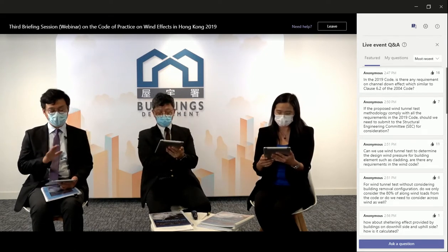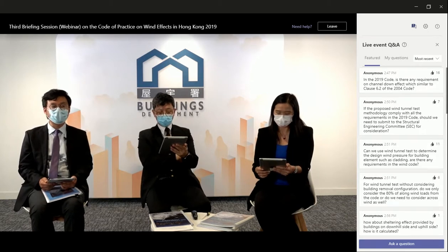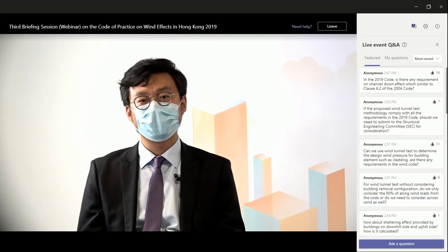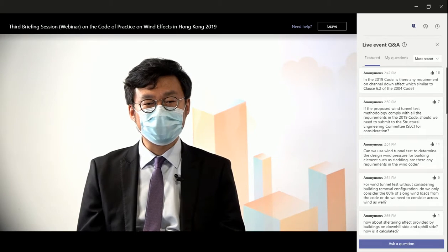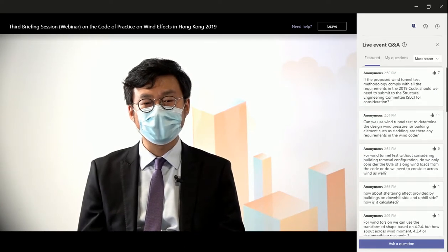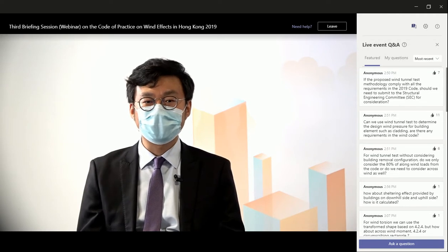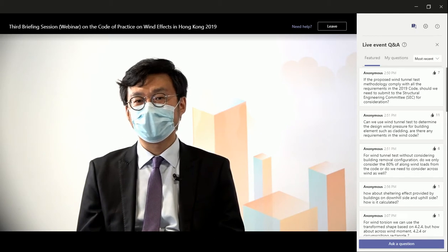Okay. So I think here I want to clarify that the wind tunnel testing can cover both the structural wind load and also the cladding wind load. So definitely we can conduct the cladding test to instrument the surface wind pressure on the entire building. So that is for building envelope design. That also includes any attachment, for which the designer or the client wants to get a more accurate wind load.